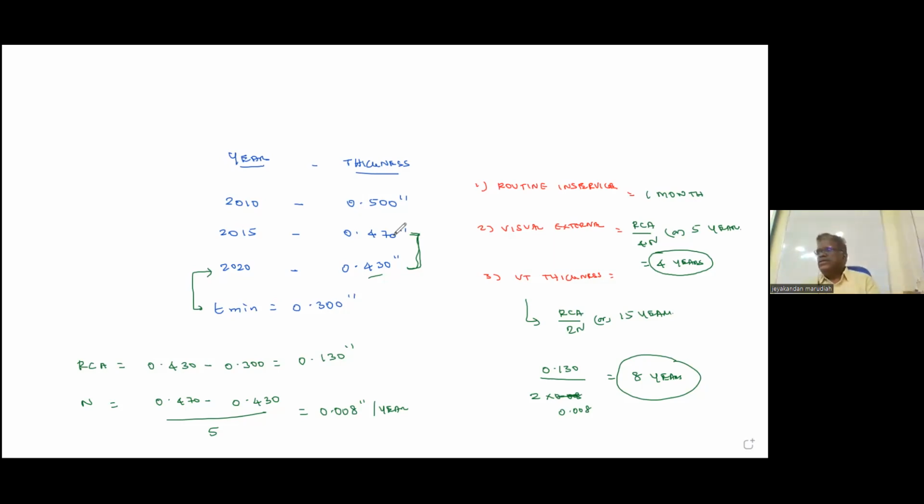Is there any internal inspection interval, something like that? Internal inspection is given for the bottom. We will see later. This is for the shell. For the shell, there is no mandatory internal inspection. The code says internal inspection is only required for the bottom. But if you are going for internal inspection, you have to shut down the tank and clean it completely. At that time you can do this inspection also if possible. But if there is no shutdown, you can see this one from outside only.